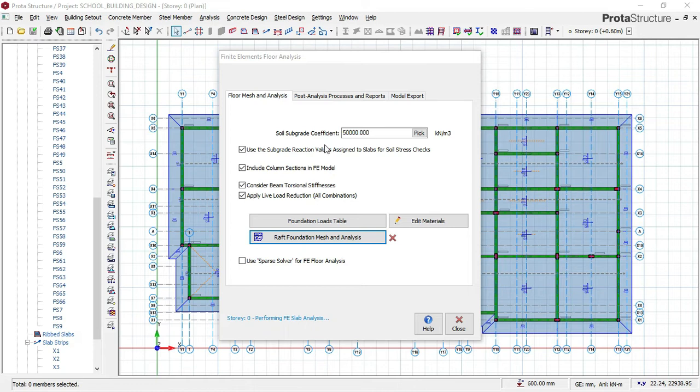Okay, and then you will also see what they call positive moment and negative moment. Leave those two values as 1, and just input your soil bearing capacity, which I have said already in our part 1. Before you make a choice for a raft foundation, your bearing capacity must be below 75 kN per meter square. Once it is above that, you have to use a pad foundation or a different kind of foundation. But once it is below, you have to consider using a raft foundation or a wide strip foundation. Wide strip foundation is what you should consider first.